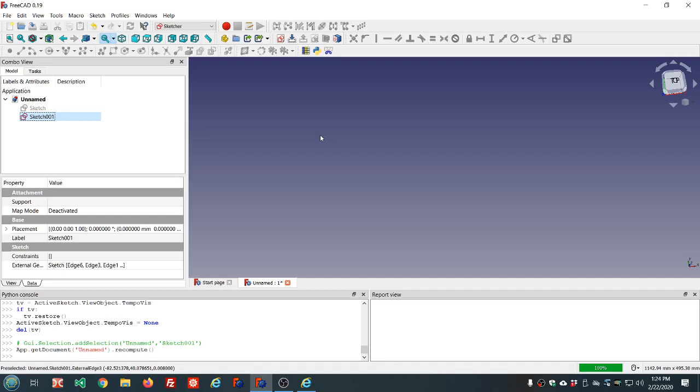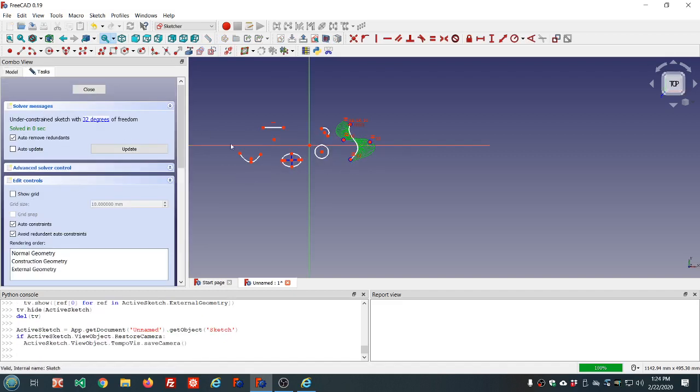Well, this type of point array, it uses the points that you create in your sketch as locations for the copies of the array object. Only the points, not the points on the ends of line segments and what have you. Just this type of point.